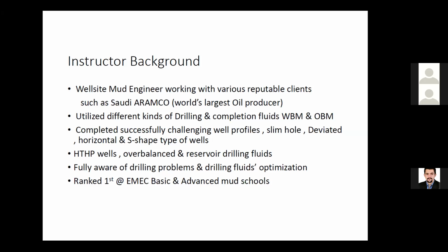And you have something called reservoir drilling fluids. Reservoir drilling fluids is about the mud drilling the reservoir. For mud drilling the reservoir, any content of the mud should be acid soluble. Should be what? Should be acid soluble, not to block the pores of the reservoir.